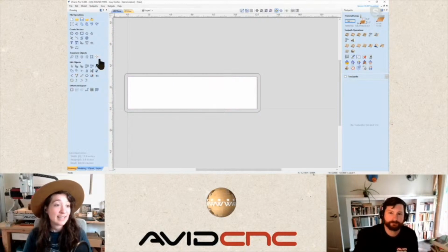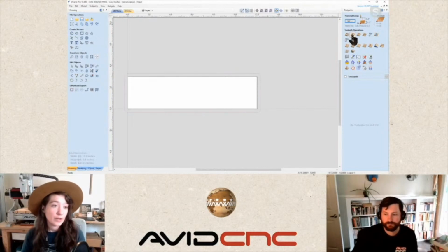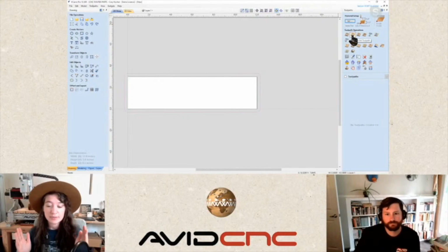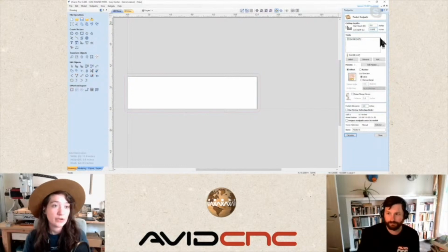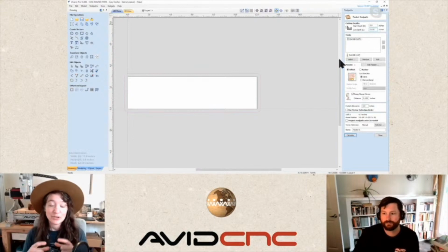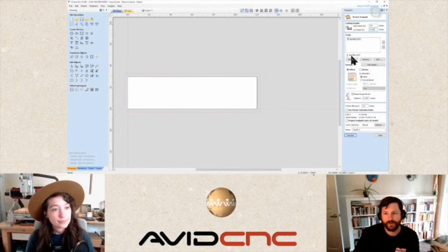Right, Sami? Exactly. Surfacing is oftentimes the first toolpath that we'll do for cleaning up a piece of raw aluminum or even wood as well. This is a really great operation to start with. I like being able to enter the surfacing from the outside of the material rather than from the inside, and making sure that the material dimension is offset just over that tool diameter is really going to help with that. Yeah. So we're going to cut down just 0.010 of an inch.